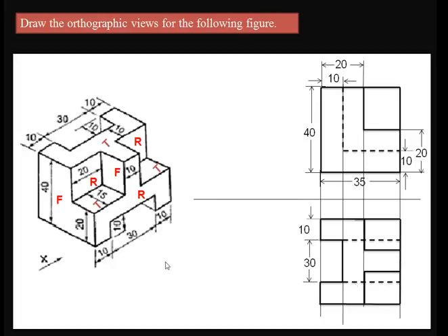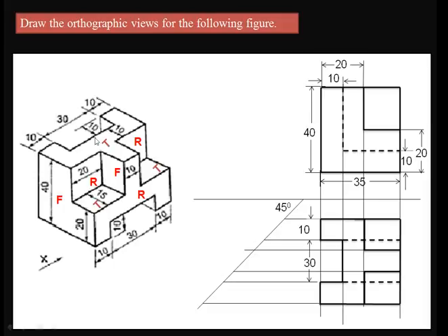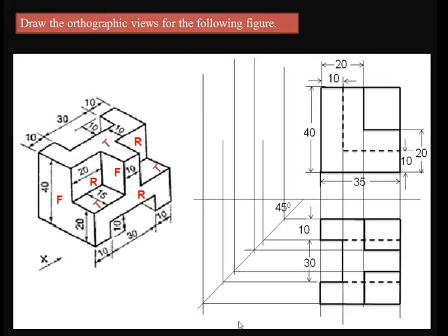So next we go for the right side view. For that, draw a line at a particular distance from the two projections we have drawn, at an angle of 45 degrees. After drawing this line, draw the projection lines like this. From each and every edge we need to draw the projection lines until they intersect the line which is drawn at an angle of 45 degrees. From these intersecting points, again draw the vertical lines for getting the final right side view. So in this I want to first draw projection lines from the front view also. Drawing the projection lines from the top view and from the front view, we will get certain intersecting points. By using these intersecting points directly we can draw the right side view.